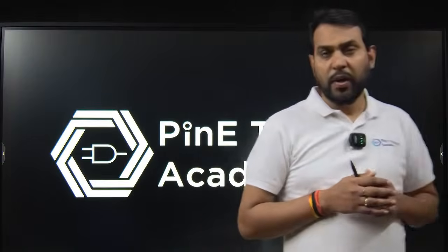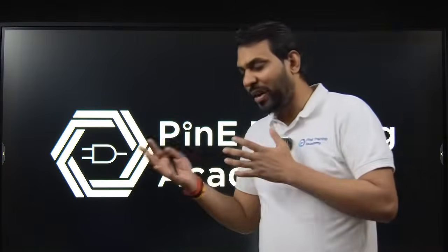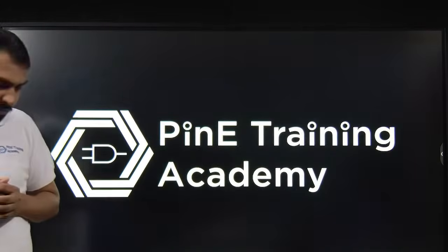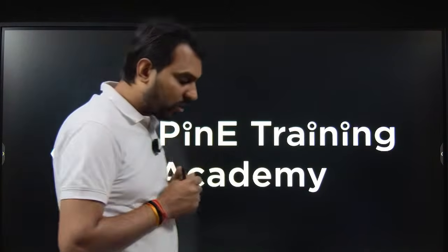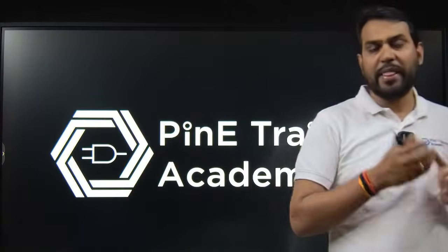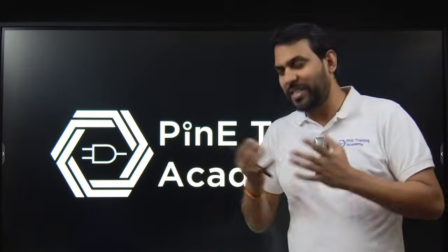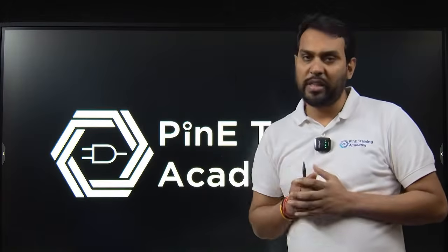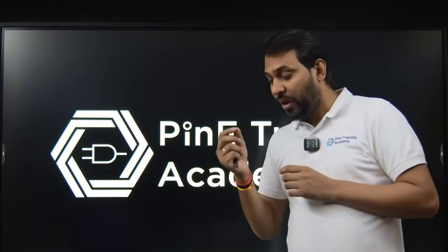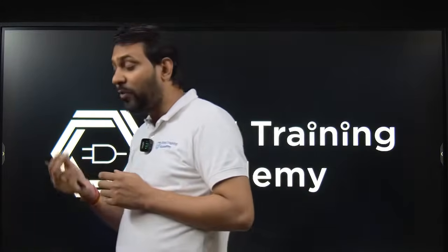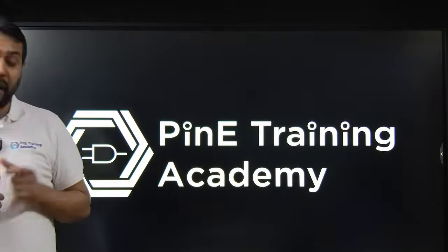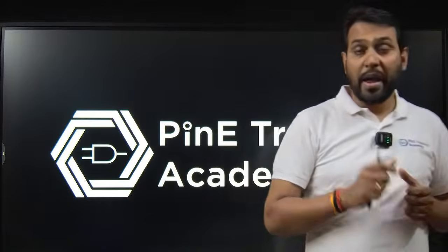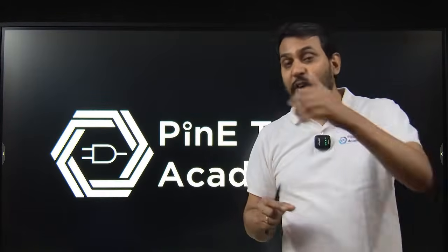And then we discussed some numericals on the basis of KCL and KVL. KVL works on the principle of conservation of energy, and we solved some numericals on KCL and KVL. And then we discussed series and parallel. What is the meaning of series? If one element after another element is connected with a simple load, that is called a series circuit. If two or more elements are connected across a pair of nodes, that is called a parallel circuit. In a series circuit, the current is the same and the voltage divides across the elements. In a parallel circuit, the voltage is the same and the current divides.